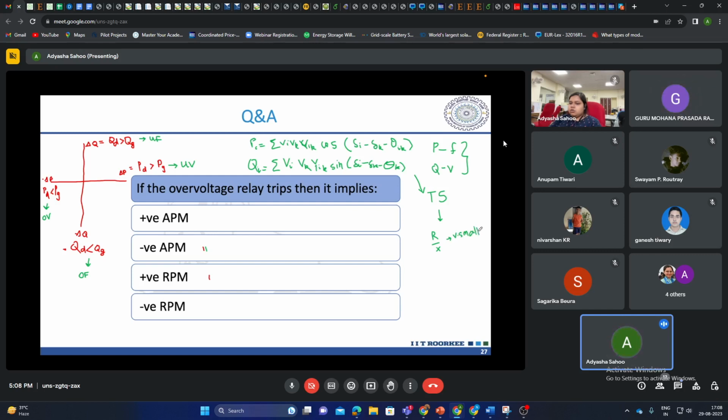If you remember fast decoupled load flow, when we went from Newton Raphson to decoupled and fast decoupled load flow, we neglected some B term. That was for the transmission system only. When you study distribution system power flow methods, such kinds of assumptions we can't take. Unfortunately, for the distribution system, the R by X ratio is not small. They are comparable.